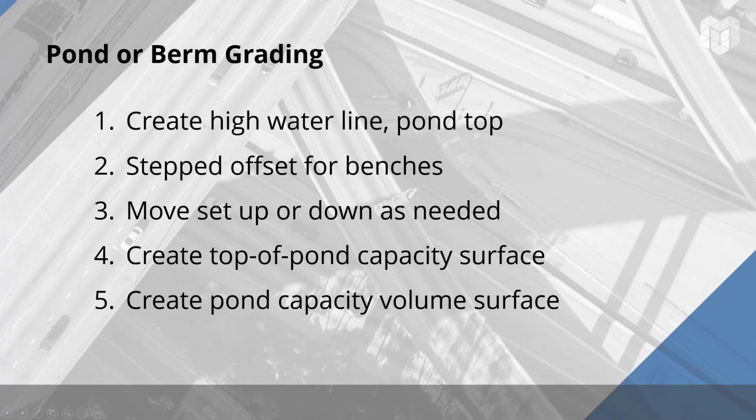We can move a set of feature lines up or down as needed if it's not at the right location. And then we'll create a top of pond capacity surface and then a pond capacity volume surface so we can understand the capacity of our pond itself.